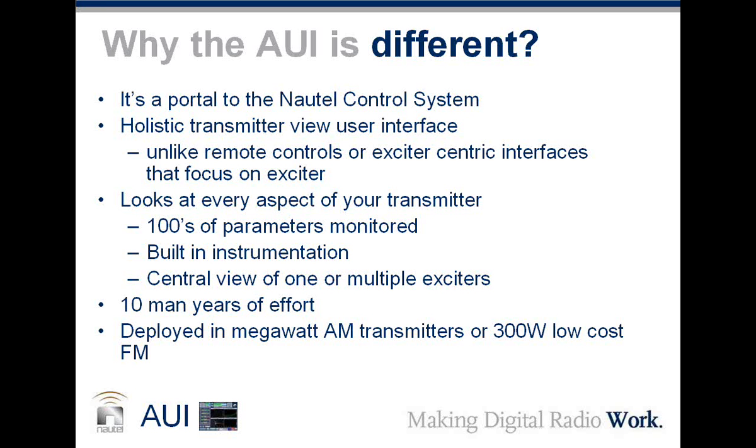But as Chuck says, the software of the AUI runs on a single board computer that's built into the door of the transmitter, but it's only interacting with the transmitter. It doesn't run the transmitter, and I think that's one of the key points. It's a very key point. We want to make clear here that it's giving you access to what's in the transmitter. Okay, so it does look at every aspect, and really it's potentially thousands of parameters which are monitored within the AUI. Absolutely. There's a lot of built-in instrumentation, which we'll see in detail. It provides a central view of one or multiple exciters.